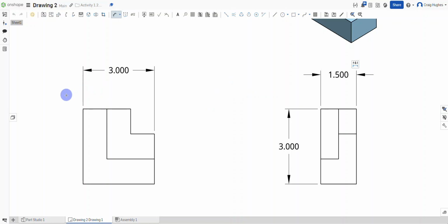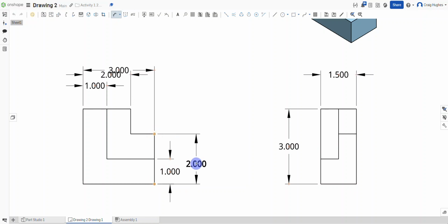The other thing is, as I showed in dimensioning, here I've got 1, 2, 3, 4 lines. That means I need 3 width dimensions. So I'm going to grab maybe from here to here, and maybe from here to here as my next one. I'm going to place that one in there, and I'll adjust those in a moment. Same kind of thing for height. I may want to go from here to here, and maybe from here to here to communicate that height. The only other one depth-wise, we just need one more to show how deep this is. 0.75 would work just fine there.